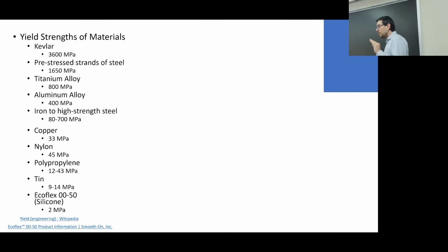What's the difference between? Well, actually, maybe the next couple of slides we'll talk about this. But is there a correlation between hardness and elastic modulus? Yeah, often, right? In order to be a very hard material, you're probably going to have a pretty high elastic modulus. Okay? But hardness is actually not quite yield strength, okay?